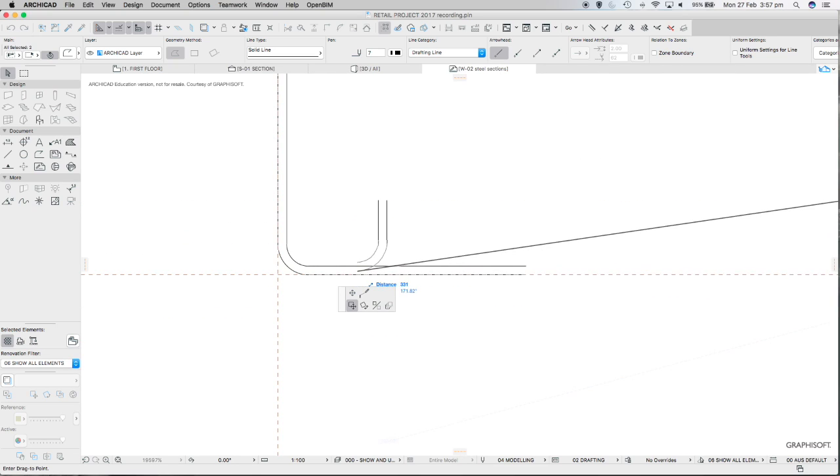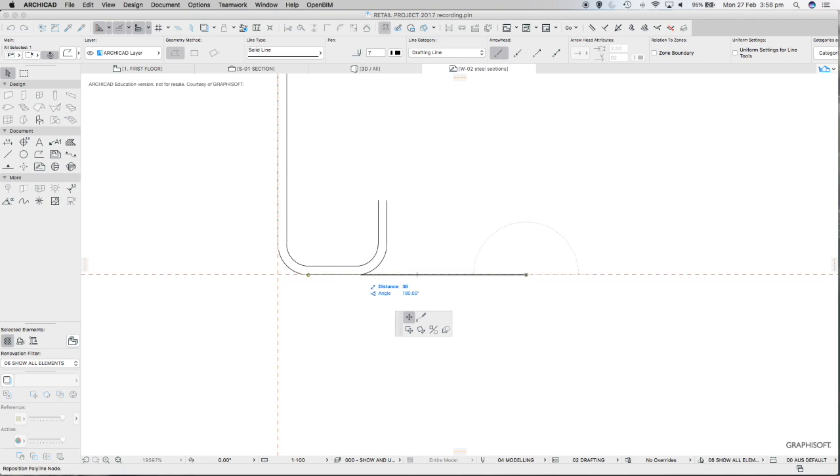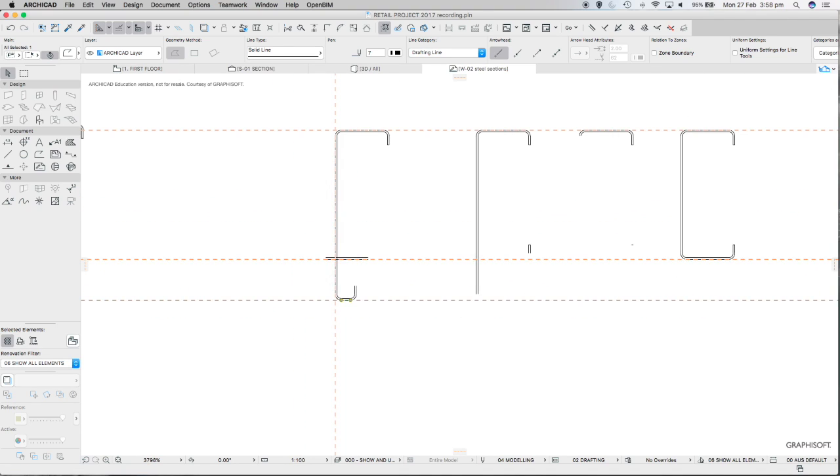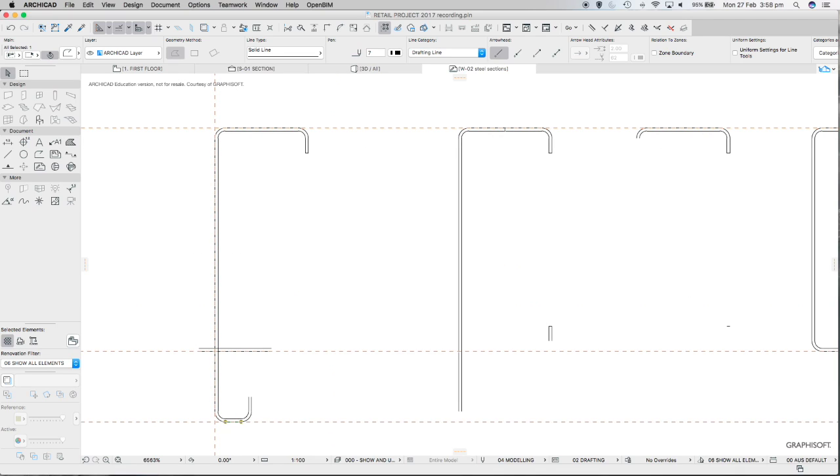And this one here is going to come to a position maybe like that initially, and then after I get it there, I'll pick it up again and then move it to there. I need to get that tip to make it work, and then I can click on the end of this line and make sure I'm in stretch to stretch that one back until the pencil changes. And then click, watch for the pencil to change so you know you've got the end point.